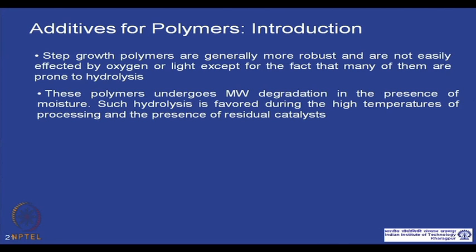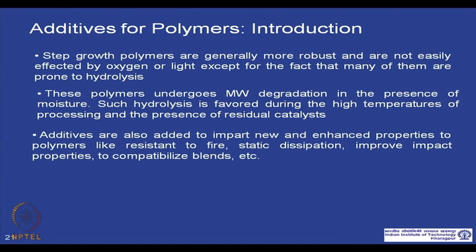So, these polymers actually undergo molecular degradation in presence of moisture, and such hydrolysis is favored during high temperature processing, and it is accelerated by the presence of residual catalyst. So, you must keep this in mind when you design additives for step growth polymers.